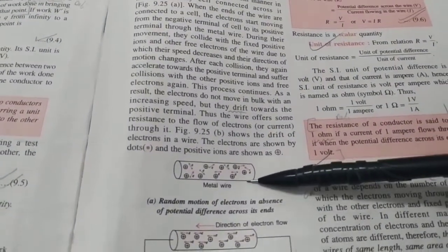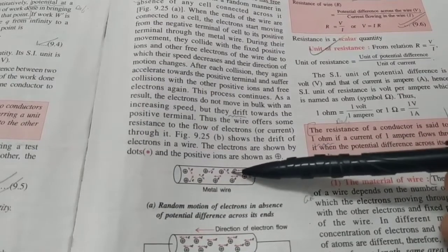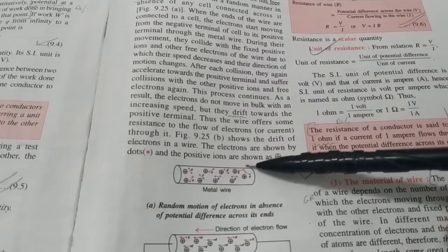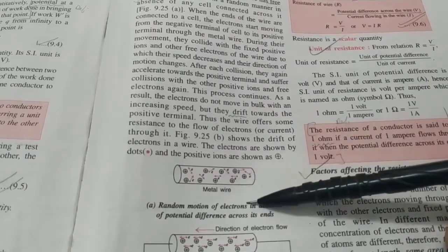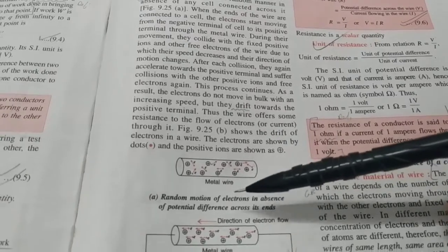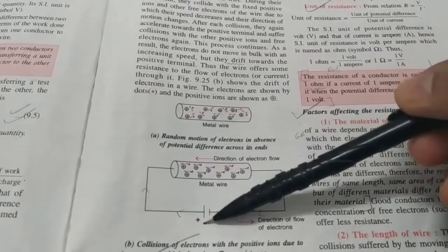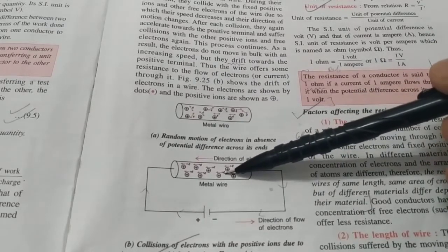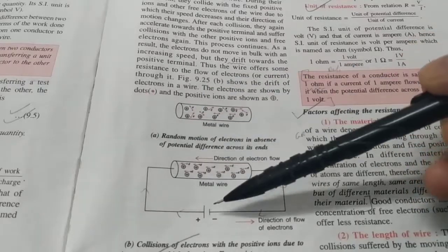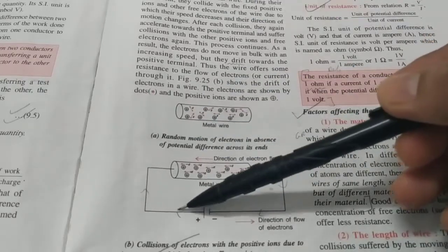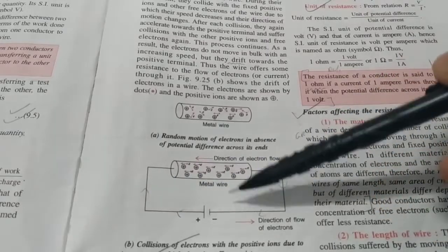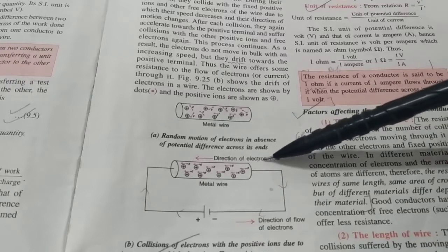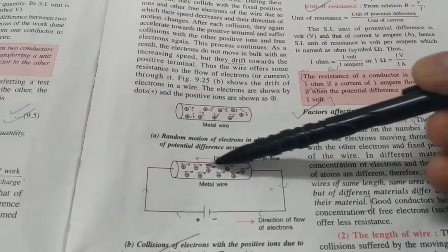In any metallic wire that is a conductor, there are many free electrons because metals have those valence electrons which can freely move about. That's why they are good conductors, because they have free electrons. However, when there is a potential difference applied between the two ends thanks to this cell or any other source of electricity, then the electrons will be disciplined and start drifting in a particular direction, which is actually from negative to positive. However, current is always marked as from positive to negative. So, because of the potential difference, the direction of electron flow is in this direction.